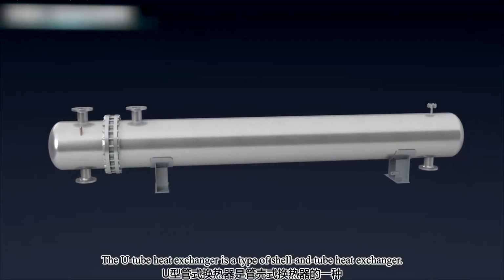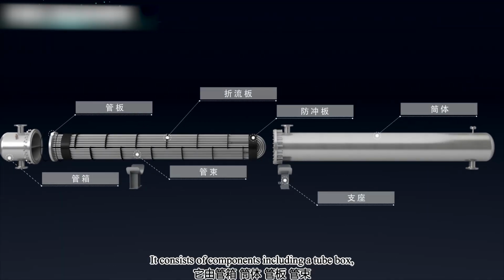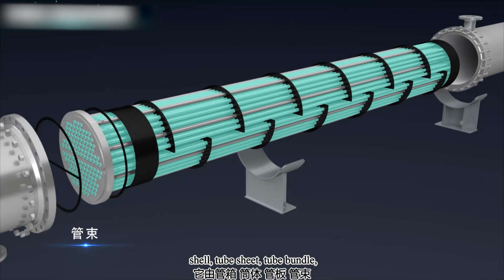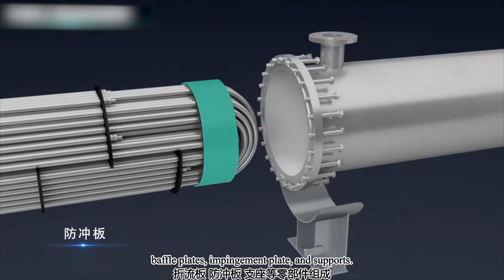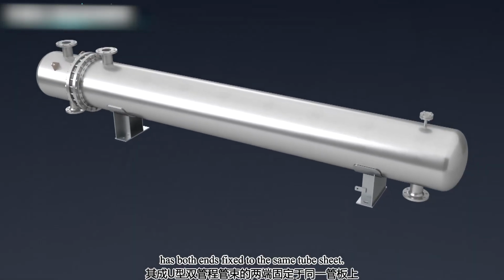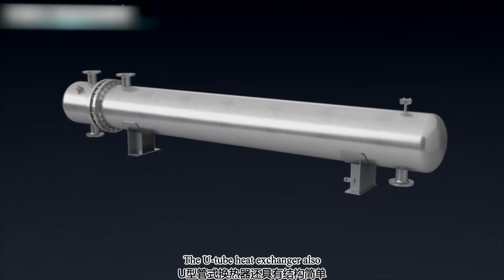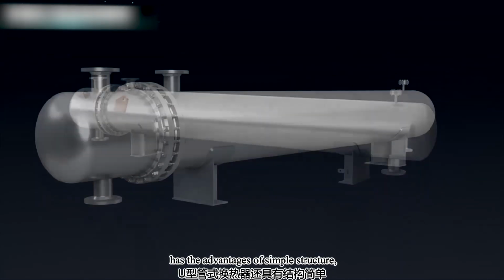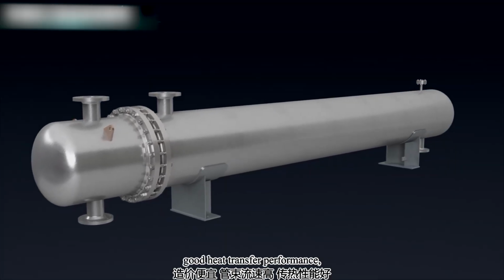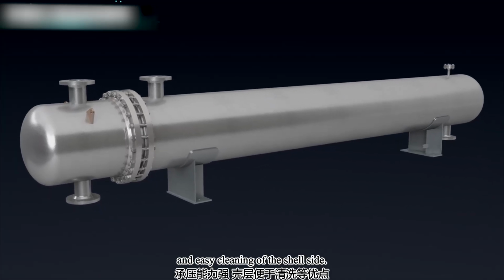The U-tube heat exchanger is a type of shell and tube heat exchanger. It consists of components including a tube box, shell, tube sheet, tube bundle, baffle plates, impingement plate, and supports. The U-shaped double-pass tube bundle has both ends fixed to the same tube sheet. The U-tube heat exchanger also has the advantages of simple structure, low cost, high tube side flow velocity, good heat transfer performance, strong pressure bearing capacity, and easy cleaning of the shell side.